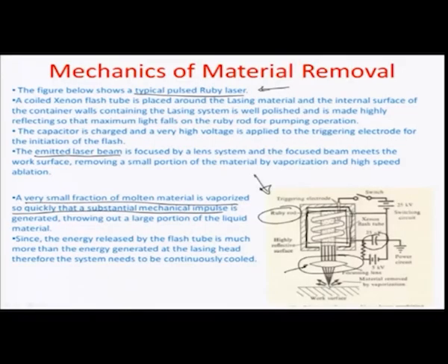Since the energy released by the flash tube is much more than the energy generated at the lasing head, you have to continuously cool this system, otherwise it may hit the melting point of some of the materials involved in developing this lasing torch. So, all the lasing media typically need to be continuously cooled for proper operation.